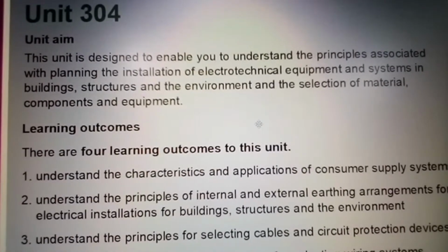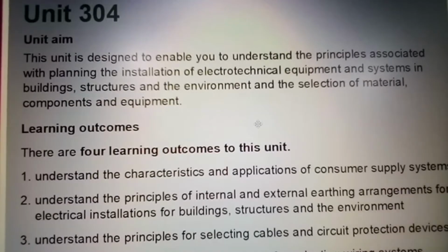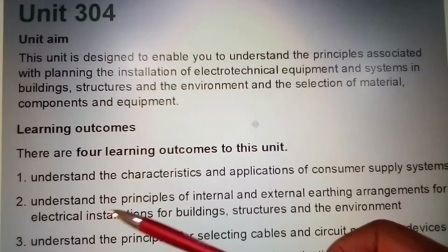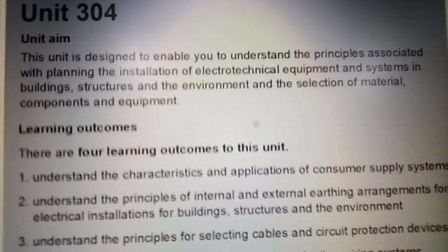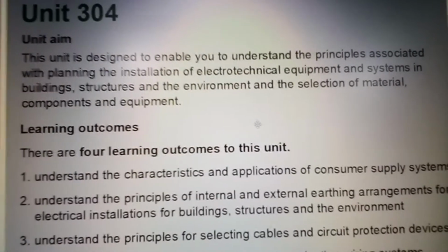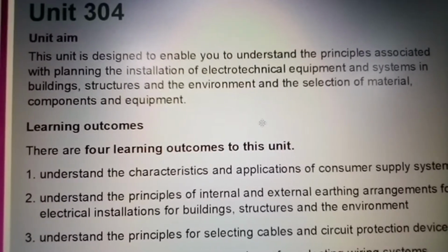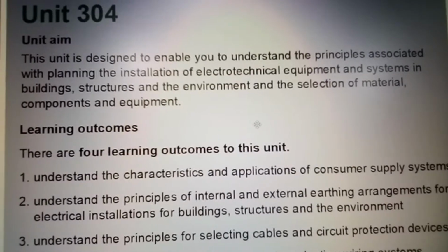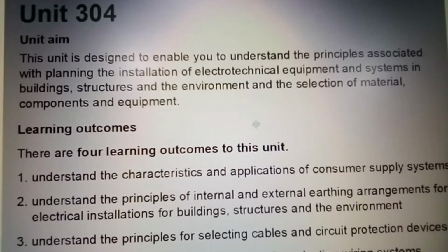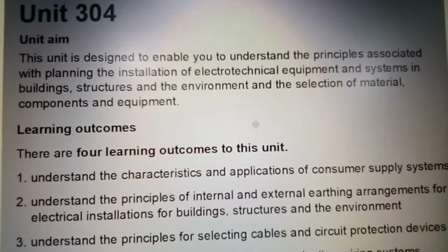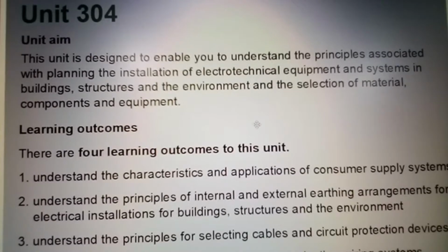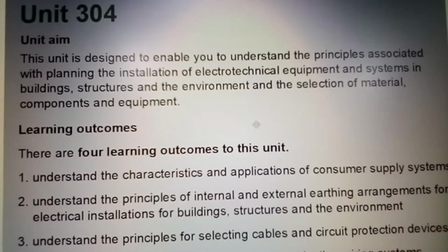Now, the problem is in the situation where the earthing is being applied. For the power supply system for electric vehicle charging, there is a view to apply a TT system, that is, applying earthing at that point for the supply system down to ground using TT earthing. So it means that you'll be putting a spike rod into the ground bonded to the equipment, or bringing in an earth from the mains supply to your electrical charger.